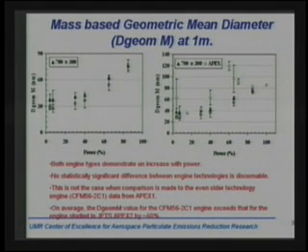That's true for the 700 and the 300 cases from the Southwest aircraft. But in the case of the engines on the NASA DC-8, when we make that comparison here on this side, there it is, okay. Then we see, actually, that on average for the CFM56 2C1 engine, which was on the DC-8, we see a larger mass-based geometric mean diameter. That's going to impact then the total mass of the emissions from that engine. And the factor there between the two is as much as 60%.